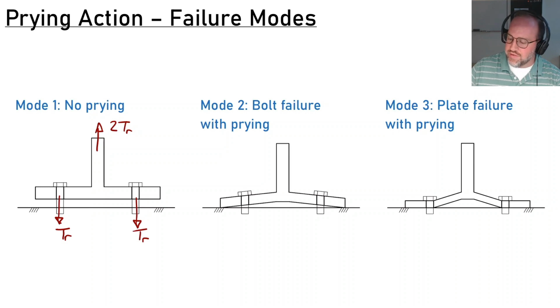Now, in this case, the bolts are going to stretch out enough, and the plate is going to be strong enough such that there is no contact at the corners. So sometimes this is known as the thick plate condition if you have that. Because there's no prying action, I'm essentially done. But in order to ensure this, I need to make sure that my plate remains entirely elastic.